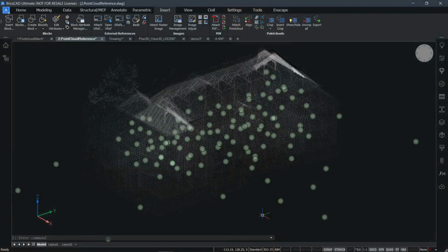The first one here is point cloud point max. Currently, if I look at the commands, it will display 400,000, meaning that there will be only a maximum of 400,000 points in my drawing. Let's change that to, for example, 5 million.